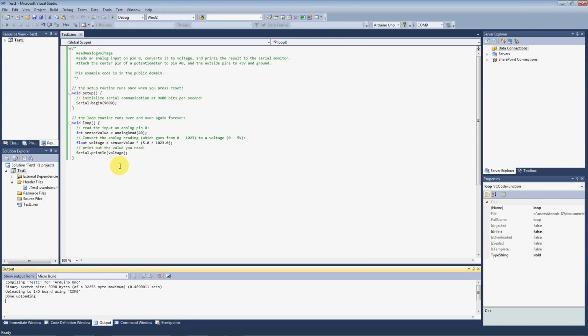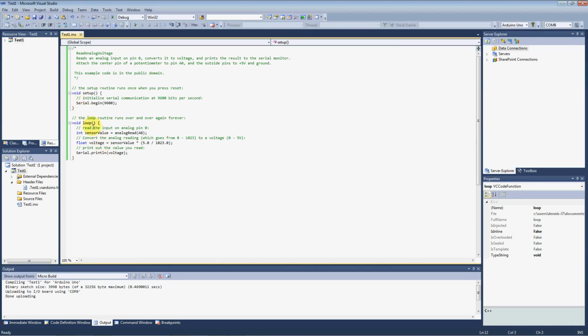Let's go ahead and check out the debugger. We'll get rid of some of these nasty serial lines here. Be good to get rid of those. And then I'm going to add a little delay line here and show off our IntelliSense. If you just start a couple letters here and press Control Spacebar, it'll bring up your IntelliSense and autocomplete. We'll hit delay, and then parenthesis, it'll show you that it just needs some kind of a number, so we're just going to delay for 50 milliseconds.